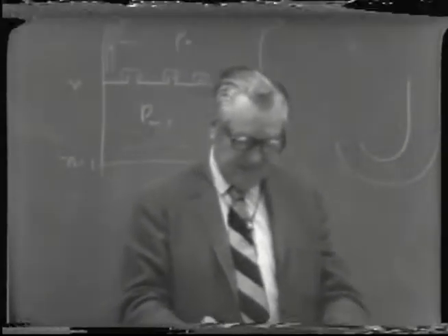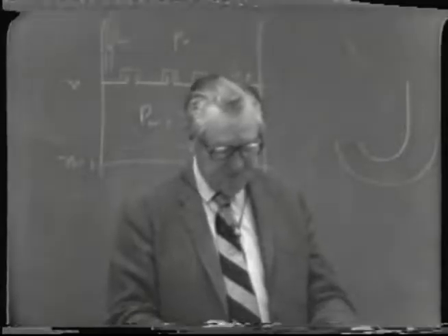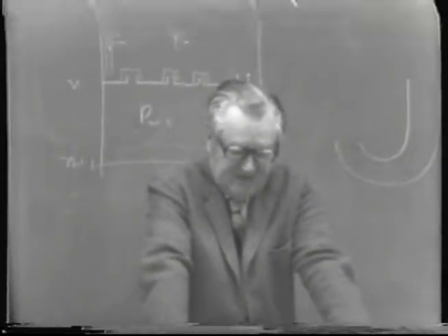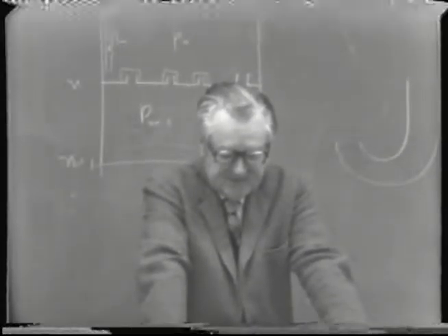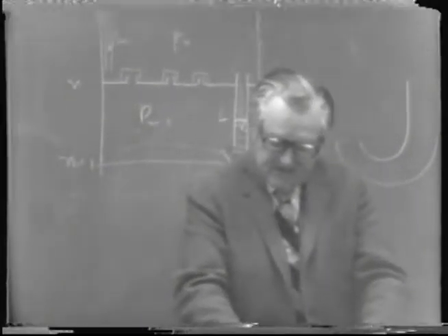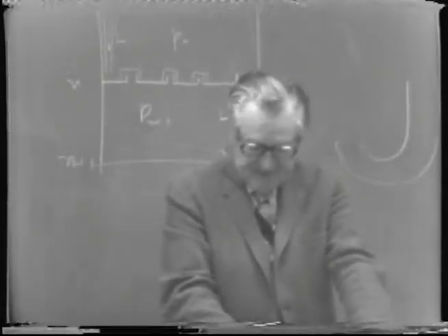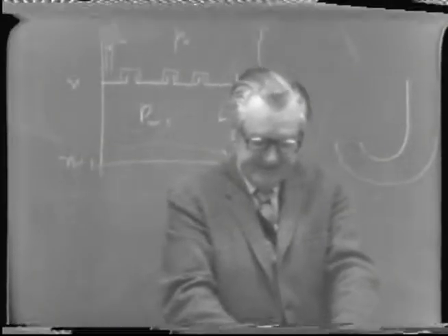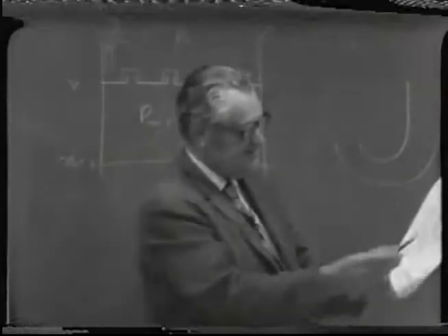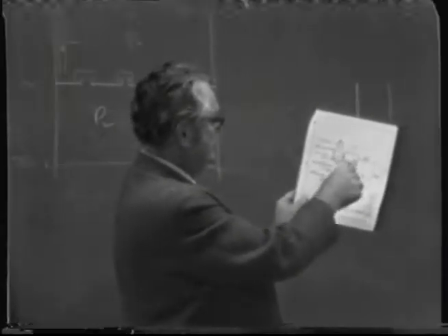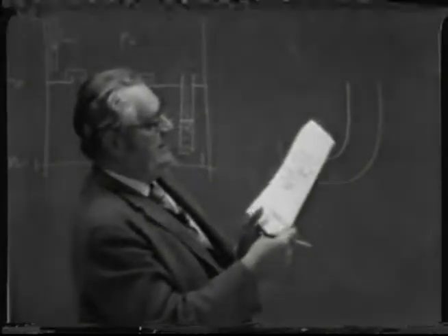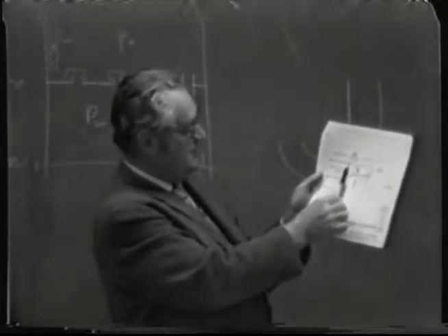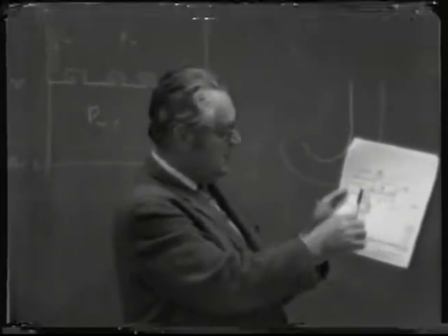It makes use of the principle of what we call thermal compression, or recompression of vapor. If you look at the diagram, you'll see at the base of the distilling column, the liquid would flow out there through that little dotted line, through the float tank, and up into the middle part of this little chamber here where the valve is shown. And this upper chamber here would have this stillage flowing into it.